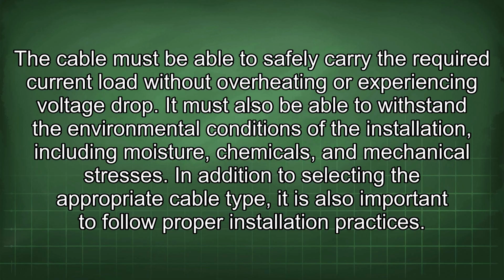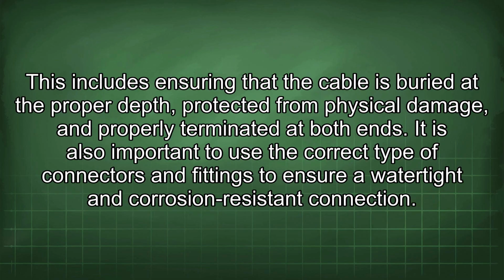In addition to selecting the appropriate cable type, it is also important to follow proper installation practices. This includes ensuring that the cable is buried at the proper depth, protected from physical damage, and properly terminated at both ends. It is also important to use the correct type of connectors and fittings to ensure a watertight and corrosion-resistant connection.